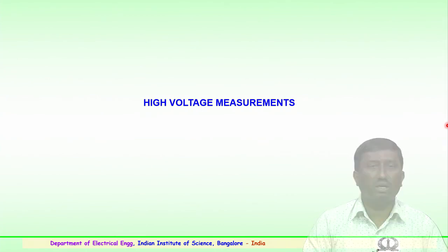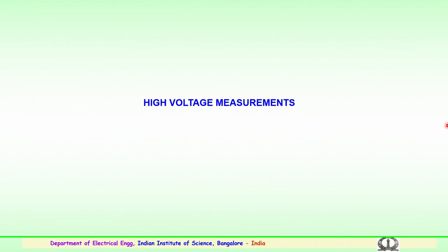This was about the basic information essential for any laboratory before equipments are tested. Equipments used in transmission at very high or ultra high voltages have to be initially tested as per the specifications laid out by the international standard organizations, and suitable testing will give information for such aspects. The laboratory should be equipped with high voltage DC, high voltage AC, and surge generators, both voltage and current.